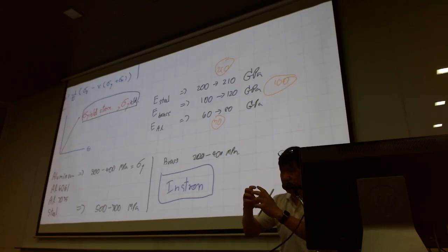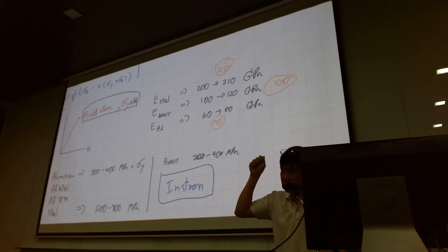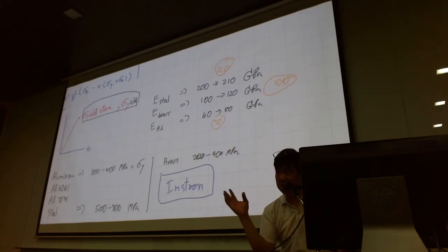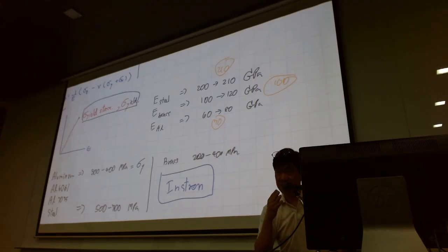And what you do is, if you have carbon elements and you freeze them very quickly, or you push them in the water, we call it quenching. You will have a different kind of metal structure. Pearlite, martensite, and usually when you have a martensite, the metal would be very strong, and that's why you get pretty strong blades when you do metal works. That is actually from the same kind of material.